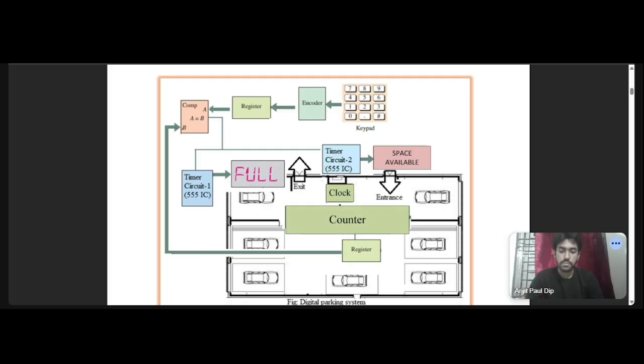In a synchronous counter, we use JK flip-flops, and as the maximum capacity got by my student ID was 13, to represent the number 13 we need 4 bits. So our counter is a 4-bit up down synchronous counter.